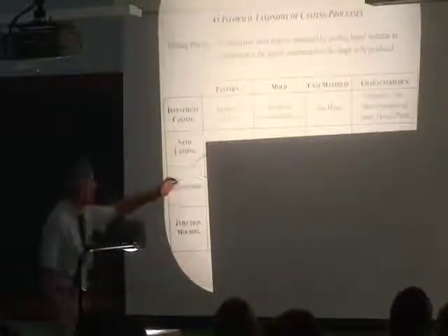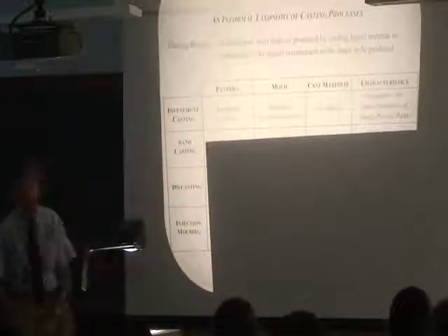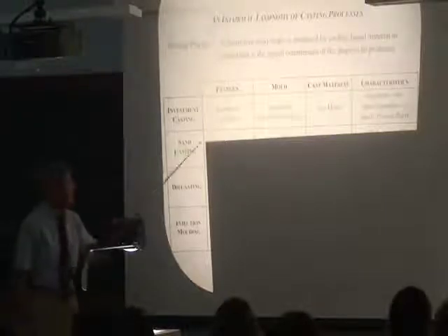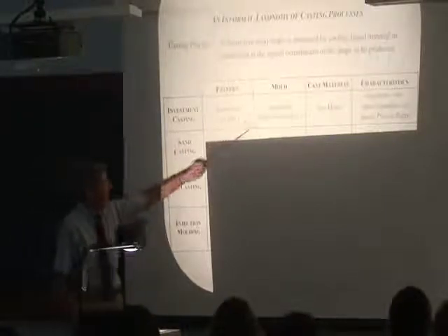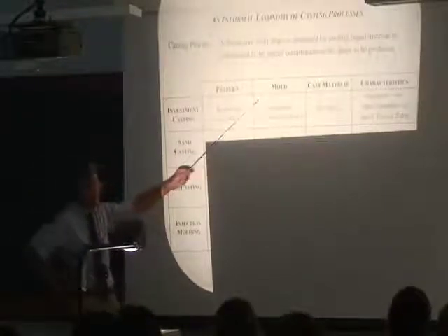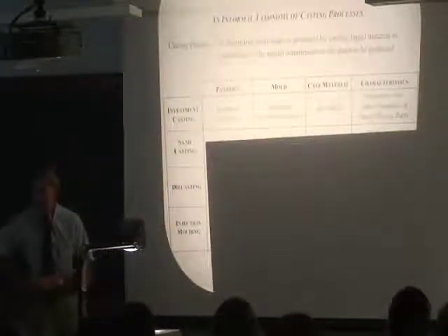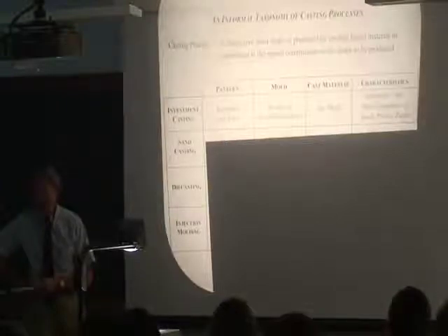Here's how it works. Your pattern is sacrificial. It means you're going to destroy it. Typically made of wax. Your mold is sacrificial too. And you take your wax pattern and you embed it in a ceramic slurry. And then you cure or bake the slurry. And so you have a very hard ceramic mold.